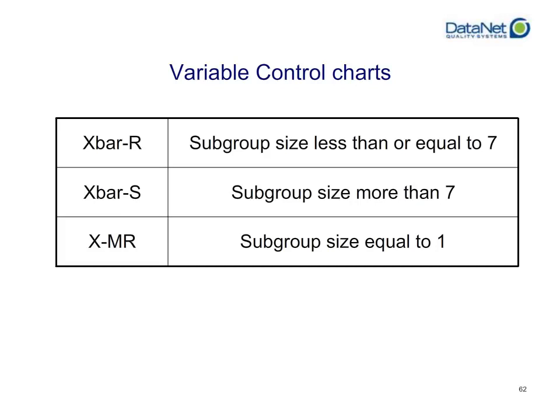As you're going to find, hopefully when you go through some of these examples, while most people tend to focus on the X-bar chart, which is your average value for what gets plotted, the volatility of your process really is captured more in your R chart, your secondary chart that really illustrates just how capable you are of producing product consistently. We'll talk about that more as we go through other examples, as well as the actual capability analysis part of the course. But for now, we're going to continue on.